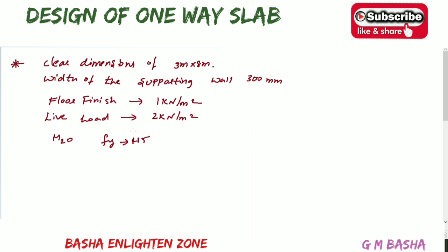And again I am repeating the same example once again. A simply supported RCC slab has to be provided for the roof of clear dimensions 3 meters by 8 meters, width of the supporting wall is 300 mm. The weight of weathering course over the slab is 1 kilonewton per meter square. Take the live load on the slab as 2 kilonewton per meter square. Design the slab using M20 grade concrete and HYSD bars. So all these are the given data according to our question, and for this data we are going to design the one-way slab step by step.